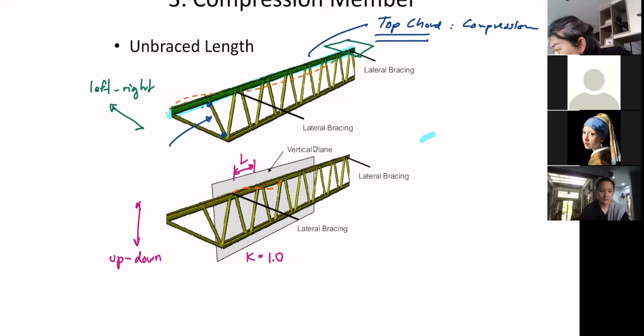It's now the horizontal plane. The web members will not be any help because now your top chord member wants to move in the horizontal plane. So the web can't help now.